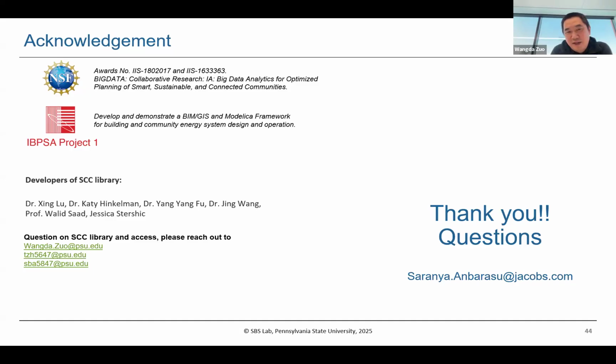Yes. Yeah, I also want to add a comment. As Anya said, the Modelica model is so realistic, right? Recently I did a study trying to simulate a commercial building with a boiler. Then my simulation stopped after a couple of days of simulation. Then I started to debug and realized I undersized my boiler, so therefore I caused trouble. So those things can help you find if the system is designed correctly. Another one is the control tuning, which is really helpful. The tuning of the PI loop is so difficult in the field, but using Modelica, you can do the exercise and you can see how you make the system more stable.